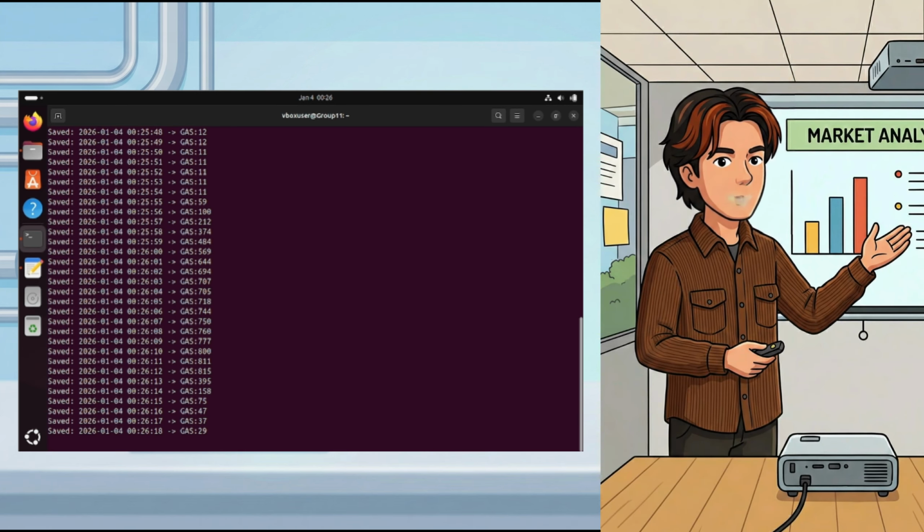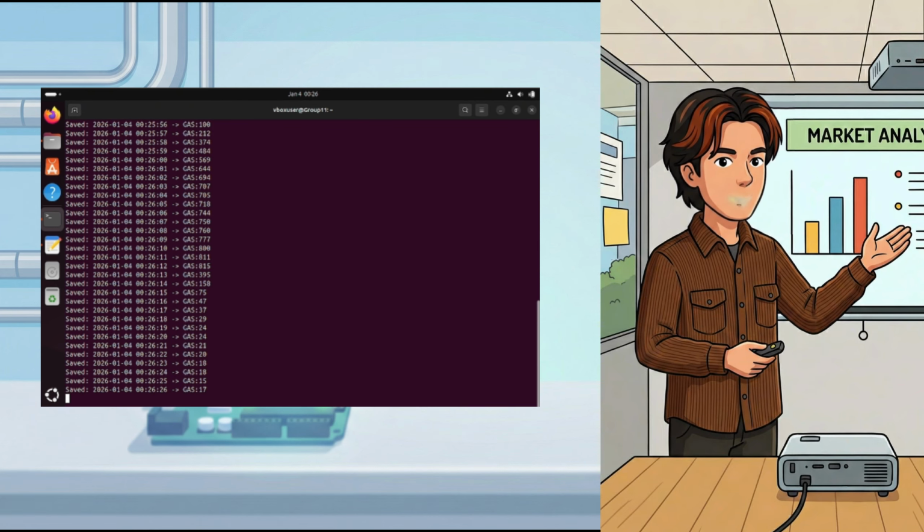After we connect the Arduino to Python, the system will start reading gas data from the PetroSafe monitoring setup using the gas_logger.py script. As you can see on the terminal, when gas is detected by the sensor, the data output immediately increases in real time, showing higher values based on the gas concentration in the environment. This proves that the sensor, Arduino, and Python integration are working correctly to monitor gas levels continuously. Finally, once testing is complete, we safely stop the system by pressing Ctrl+C, which halts the data logging process and ends the monitoring session.